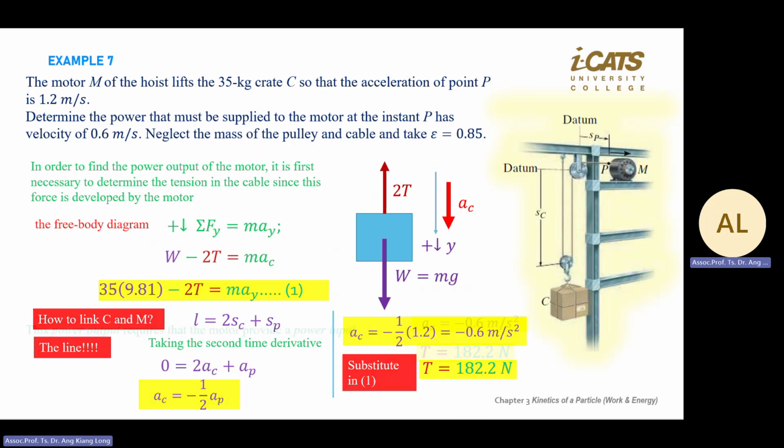Okay, all right. Now, if you see these slides, every time you draw a free body diagram and kinematic diagram, usually you can solve tension. If it's involved with a pulley, then we will solve tension. If no pulley and it is on the ground, normally you solve normal force. Then normal force, then you solve friction force. Usually like that.